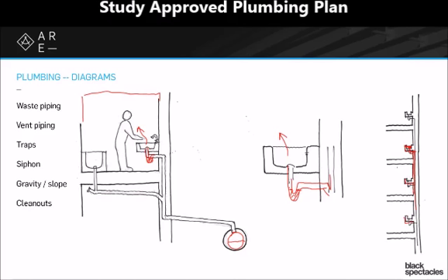What's it going to do? Well, it's going to just siphon that trap and pull that water right out. So as that water from above is rushing by, it's just going to siphon this water right out of the way and follow the water from above, sort of flushing right on through.